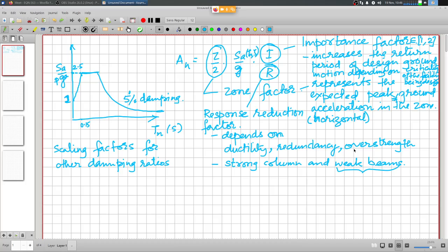and we are trying to impose an upper limit on the yield strength while qualification in IS codes, but obviously the code committees are dominated by steel manufacturers, and they are not really interested in imposing that upper limit, because that will increase their costing.